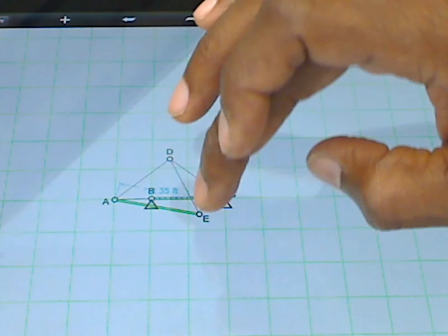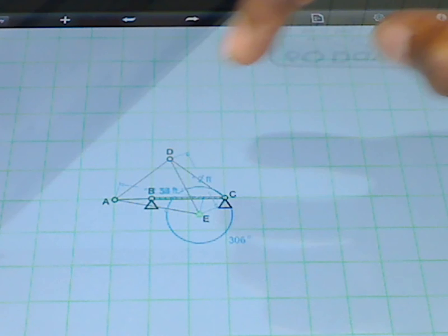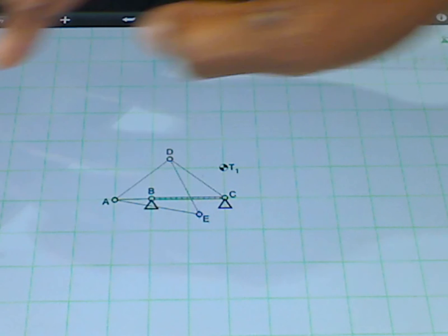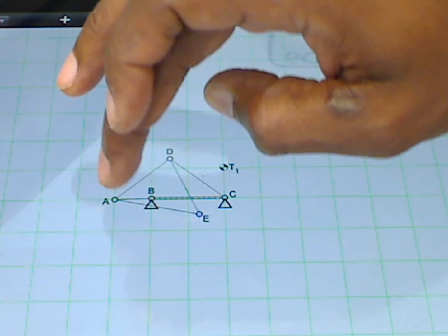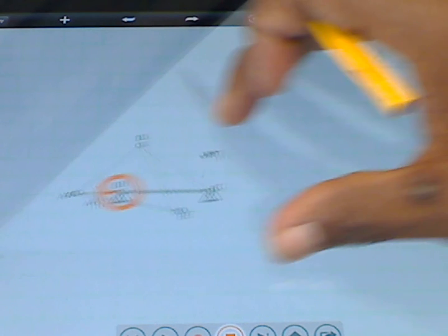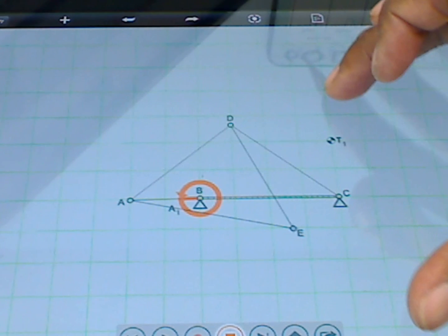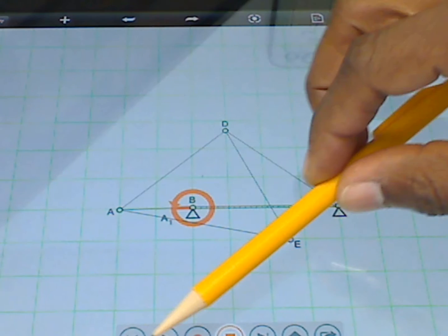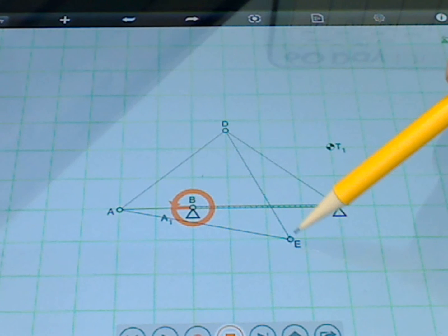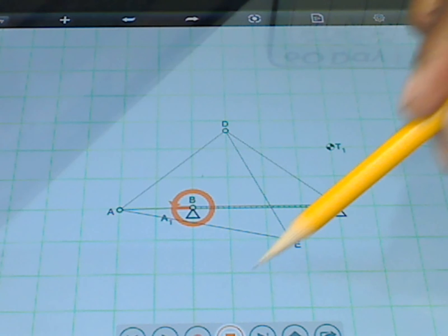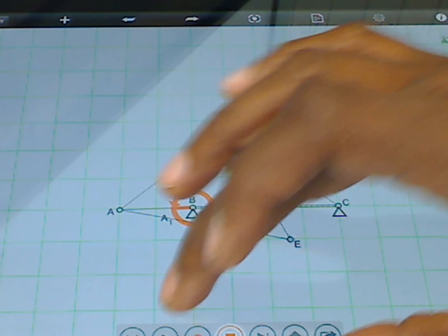I'm going to make sure that the coupler point is a point that will trace out a path that we'll be able to follow. And there we have that. We also are going to give ourselves a motor at that location. Let me zoom in a little bit and make it a little bit bigger. Since we did draw with our crank collinear extended, we can see that our line of symmetry is going to be right here from the point P, our coupler point, through our ground point 04. So we'll have a symmetrical kind of figure 8 type coupler path.